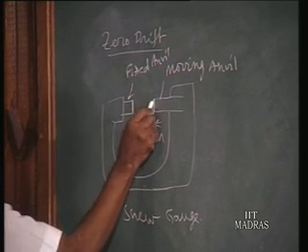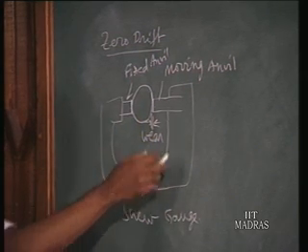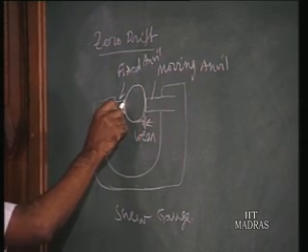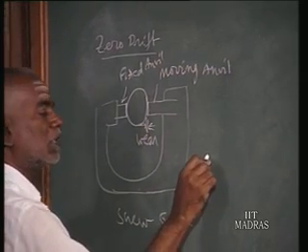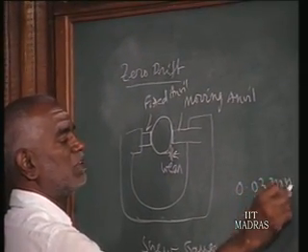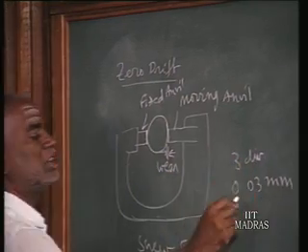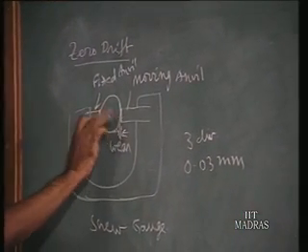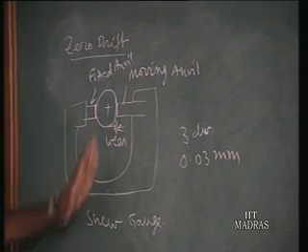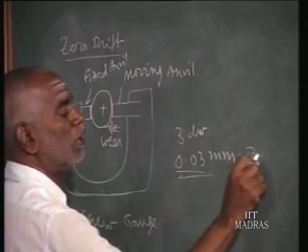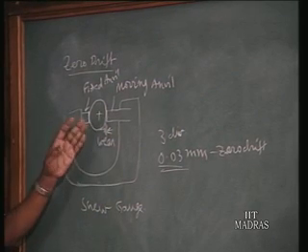So when we use this instrument to take the reading of the diameter of a workpiece, before bringing the workpiece, bring the anvil and make it touch the fixed anvil, and note down the reading. Probably it may be 2 or 3 divisions. So 3 divisions represent 0.03 millimeter, because 1 division in such a micrometer is 0.01 mm. So 3 divisions it is below, which means 0.03 mm you have to add. So you take the reading after putting the piece, and whatever the reading, add this 0.03 mm to get the correct diameter of the piece. This is your zero drift. It has taken place due to wear and tear.